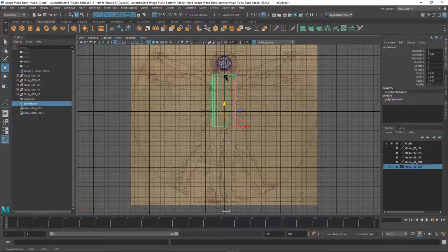All right, so now I notice maybe it's a little too tall. Maybe I want to move it down a little bit. So I'm going to go back to scaling. But now if you notice, it's going to scale from this endpoint at the end of the object. This is very useful in general, especially for limbs on a character or something like that, because these are pivot points, they're axes. So you definitely want to generally have it scaling from something like that.